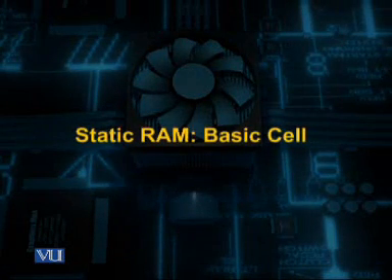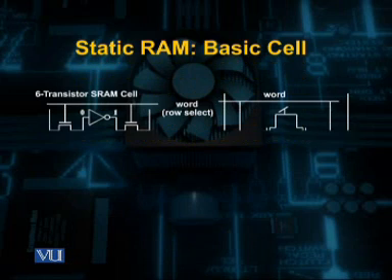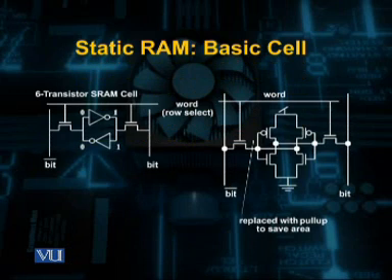Now let us look into the design of a static RAM cell. Here, each cell stores a bit of information in a circuit made of 6 transistors. This circuit retains a bit value indefinitely as long as it is powered up.